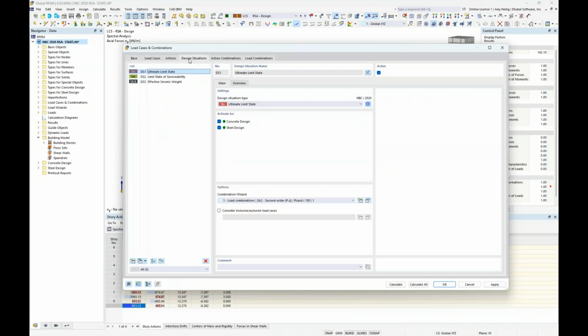And the reason why is because these load combinations are being generated according to a nonlinear second order analysis to consider those P delta effects. But we know that we cannot simply add the earthquake loads to these additional load cases using superposition, because we can't combine second order effects and just add them together like P delta.